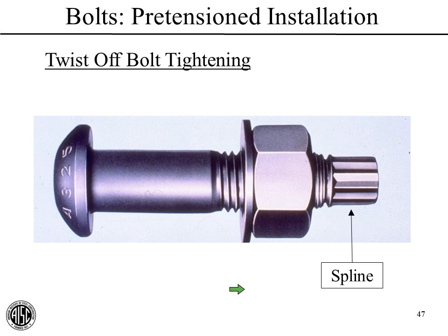And once it does that, then the bolt is at the proper pretension, or at a pretension that exceeds the minimum value at least. Now, note that we are relying on a certain coefficient of friction in these threads, so we need to take care of these bolts to guarantee that we have the correct surface on those when they're installed.